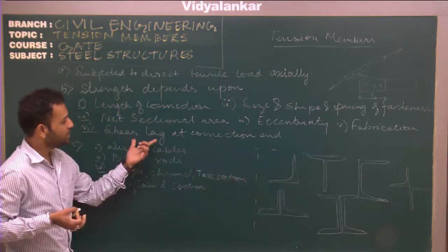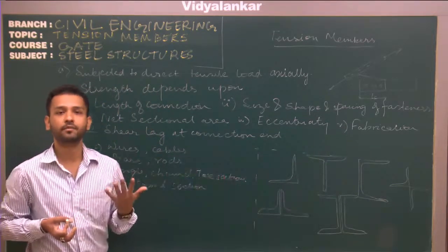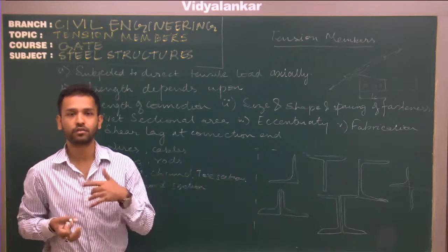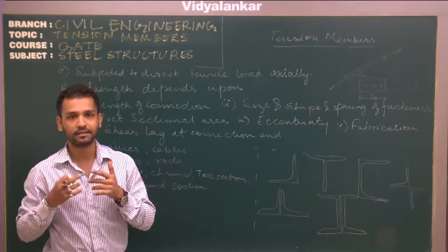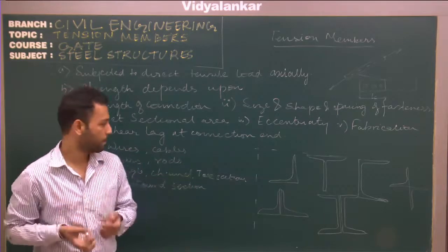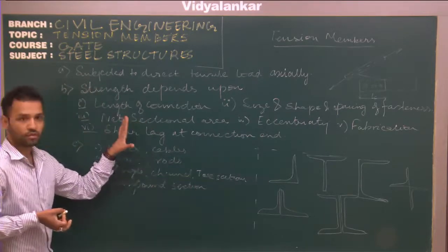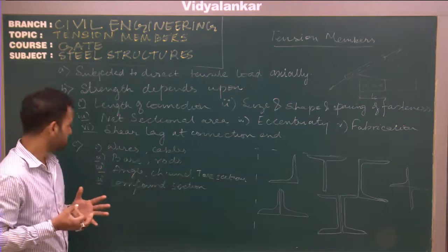Shear lag in the connection end. If the shear lag in the connection end is high, it means the non-uniformity is high and therefore the efficiency of the tension member is lesser than it should be in actual. So these are the different factors on which the strength depends.